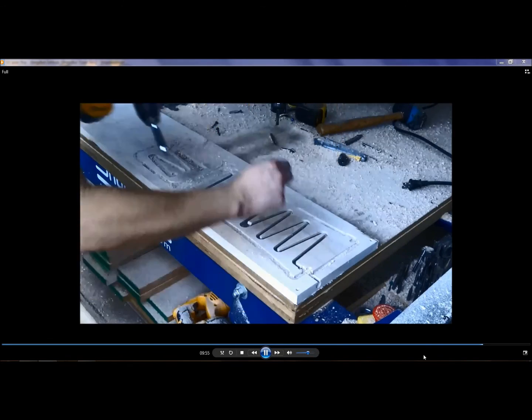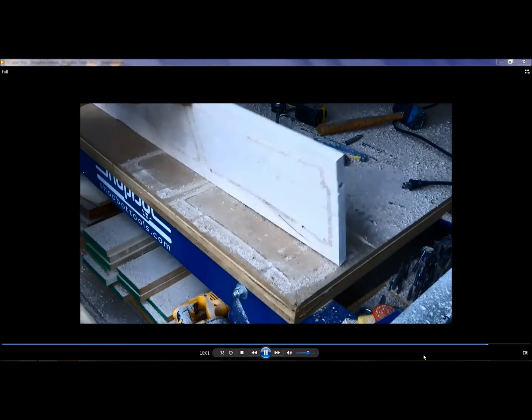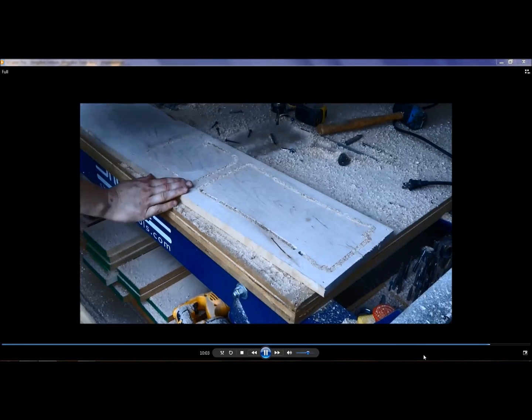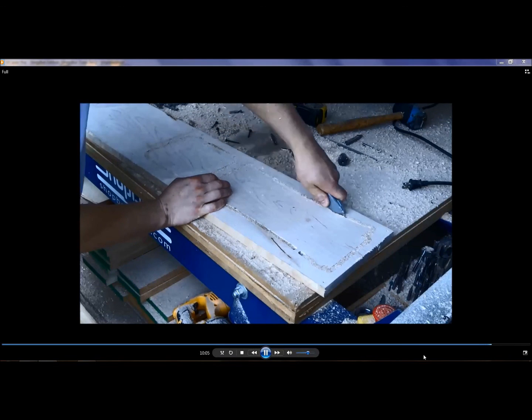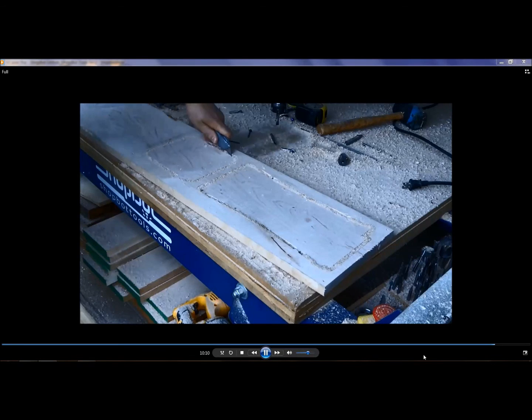And then you verify that your material has been cut all the way through with the profiles before you remove the screws, because with this method you're not going to get it back in place. Flip it over. You've got those 4 tabs that we put on each piece. Hopefully we've left the tabs big enough that they've held the part from moving, but small enough that I can just nip them away and clean them up easily by hand.